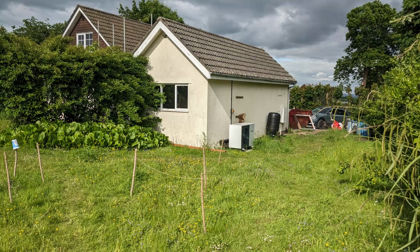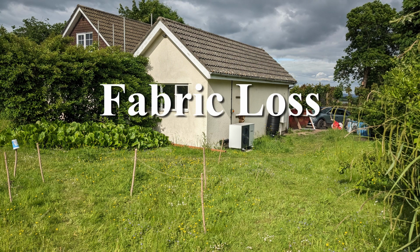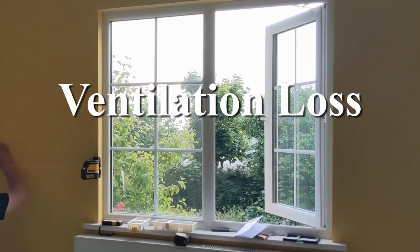In basic terms, there are two major sources of heat loss from a property. One is fabric loss, so that's the heat loss through the floor, walls, windows, doors and roof. And the other one is ventilation loss. All properties do need to have some ventilation, and that's just how many air changes an hour there are and how much energy it takes to heat up that air.